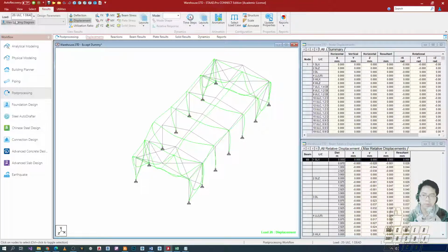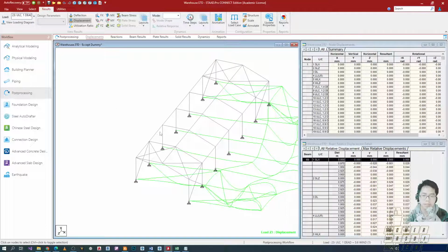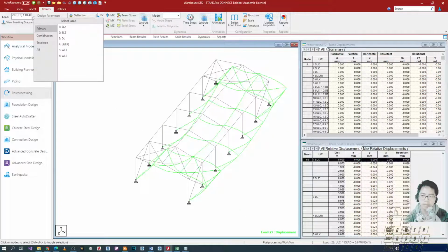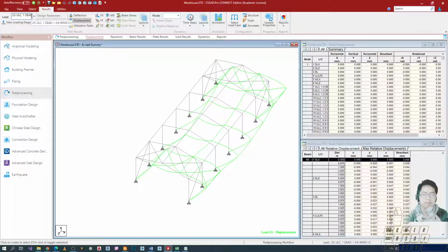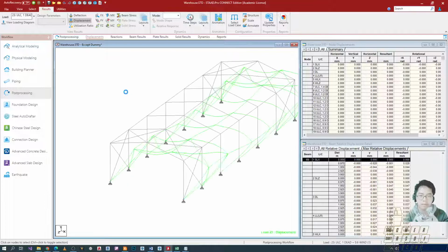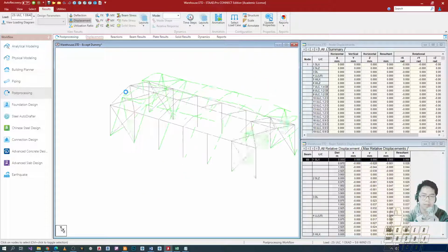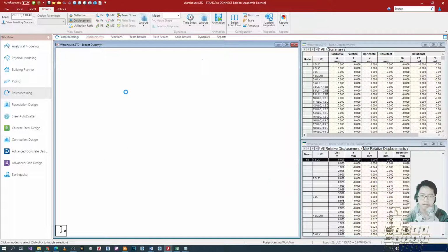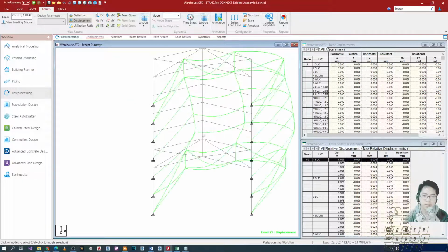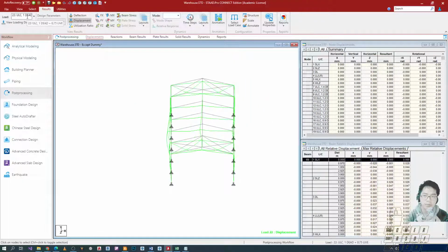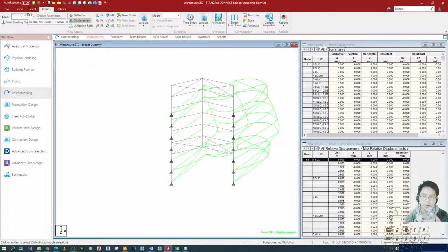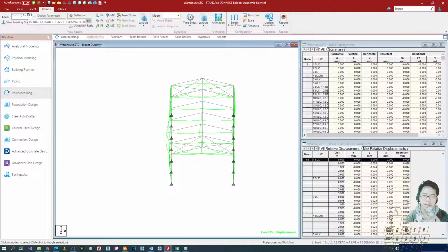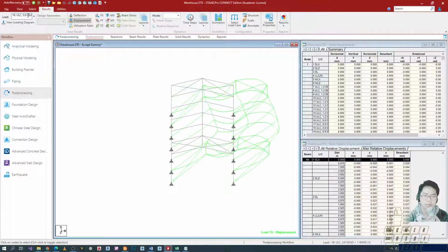And then we can just view all of our loads. Here, this is dead load plus, what is this? Plus wind along the X. So it looks right. The impact of wind looks bigger than that of seismic. Here we observe that the wind effect is larger. The X seismic is only this small, while the wind is like this. The discrepancy between them is large.